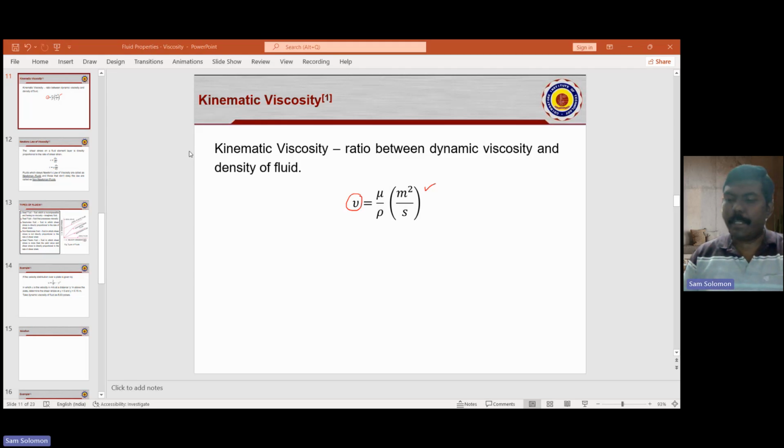In the last lecture, we discussed fluid properties. We talked about density. So just to recall what we have done in the previous class, density is mass by volume. Specific weight, we defined it as weight divided by volume. So that is mg divided by V, and mass by volume is rho, so we call it rho g.